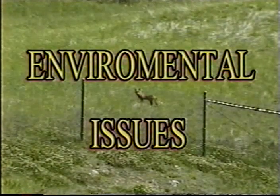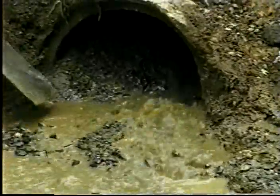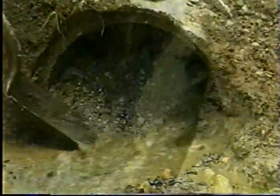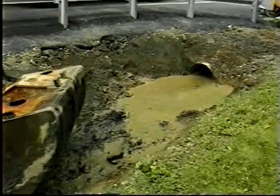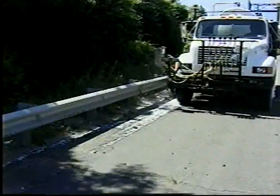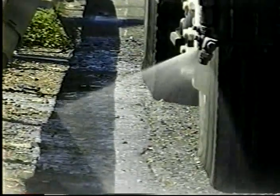In the performance of some of these routine maintenance activities, several environmental issues arise, including pollution and permitting. Several types of pollution can occur in adjoining waterways, including sedimentation, turbidity, and toxicity. Maintenance activities that cause sedimentation and turbidity include repairing slopes, cleaning ditches and channels, repairing drainage structures, and other repairs performed on the right-of-way that produce loose materials that can be washed into the waterways. Vegetation control is the primary maintenance activity that can introduce toxic materials into adjoining waterways.